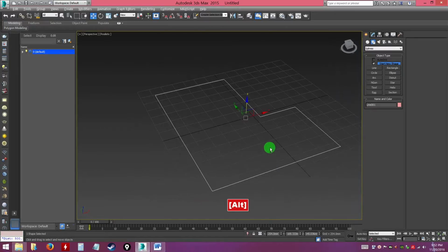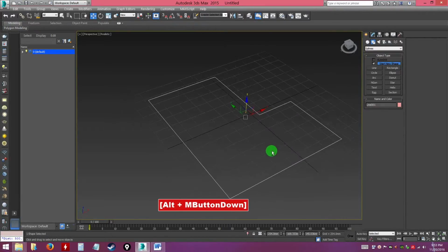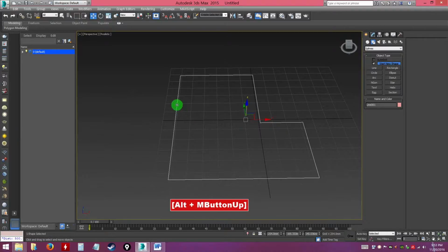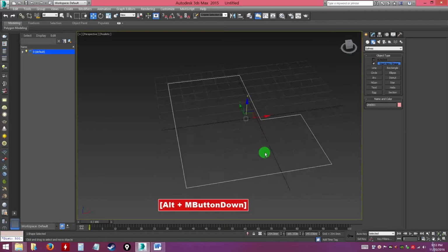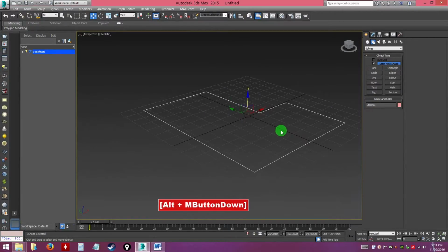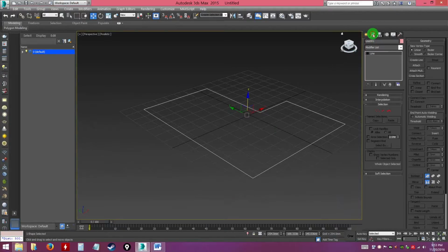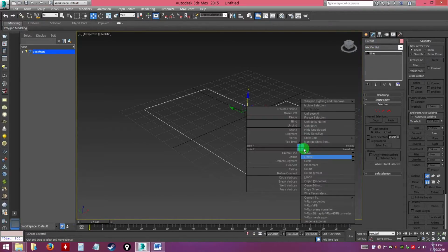You always use polyline if you want a nice conversion from AutoCAD to 3D Studio Max, so that it is not just separate lines, it's actually a conforming line that is combined together, so that you can actually build. Imagine, for example, this is the floor. I can make this floor into 3D by going to my Modify panel. Right now you see this line here. I can right click on the line and convert to editable spline.